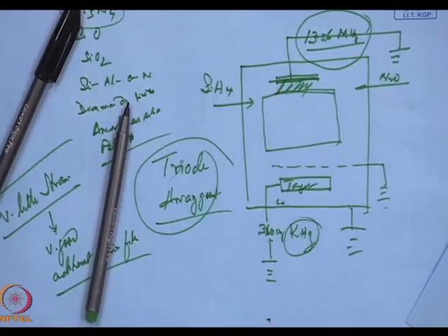That is one problem. However, if the hydrolysis rates can be matched, then the alkoxide route gives us unprecedented power to modify the composition of the film and look at various properties for which it may be used. The second method I had talked of was thermal spray pyrolysis.